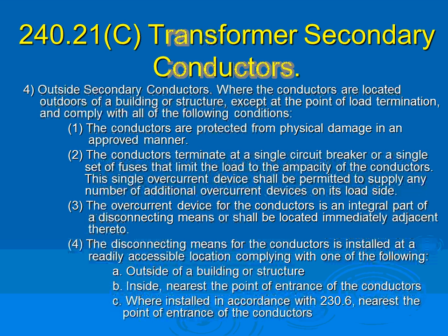The only decisive factor you have to pay attention to is short circuit. You can tap any conductor from any conductor outside as long as the overcurrent protection device can protect that conductor from short circuit. Number one. And the conductor is protected from overload by a fuse or a circuit breaker. Then you can tap and go as far as you want. No limitation on the distance if you're outdoor.